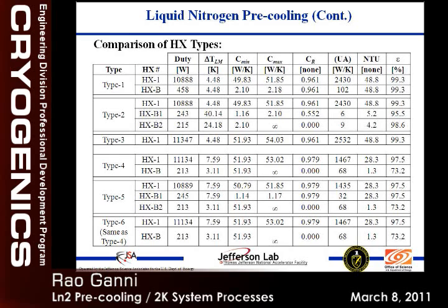It becomes that much bigger in size because as this ratio gets smaller and smaller, that means it is easy to change one side's fluid property. One end of the delta T will open up as this ratio is smaller. So if you calculate UA, or the amount of surface area you need for each type, it will tell you approximately how much you have to pay based on the UA.